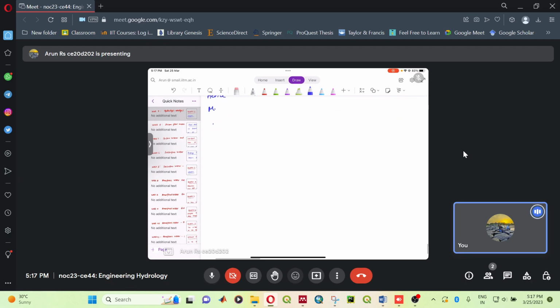So we use a modified formula, that is TP is equal to 22 by 21 into TPR minus TR by 4, that is equal to 22 by 21 into 37 minus 6 by 4. Now we have TP as 37.19 hours. Once we get this, we can estimate the coefficients.